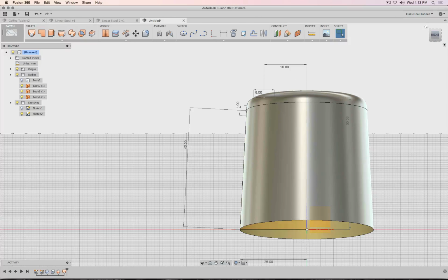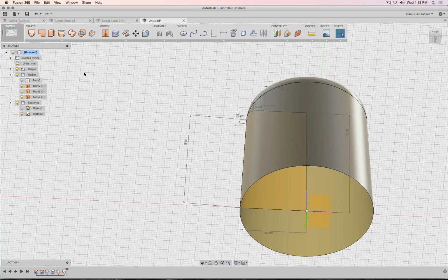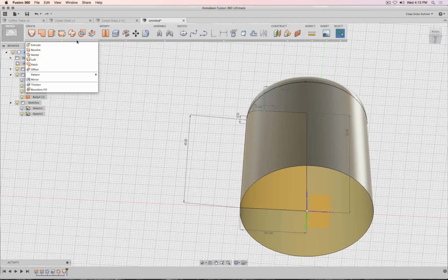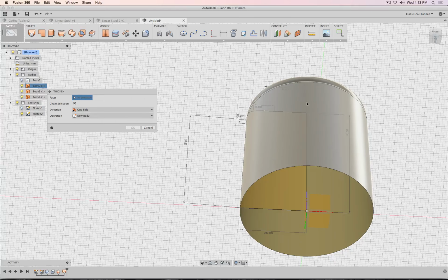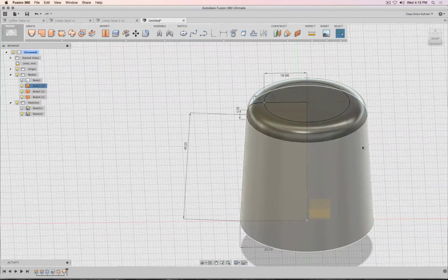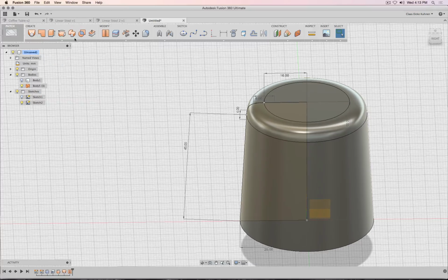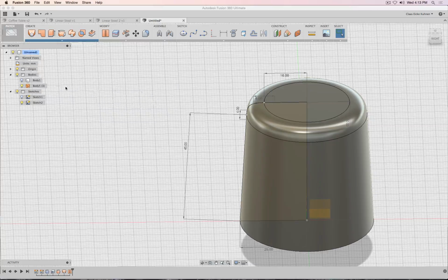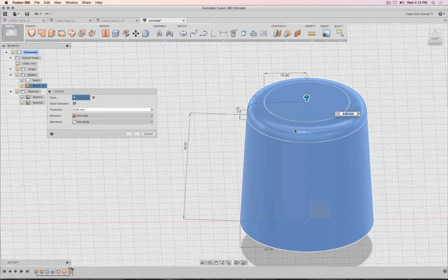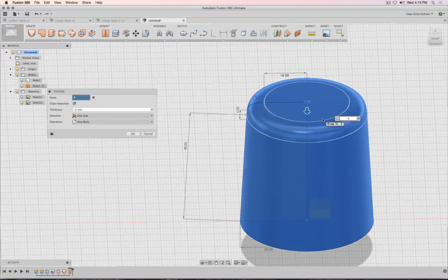There. Now the only problem is I have to create a thickness to it. So thicken this whole part, but it's actually not stitched. So I would have to stitch all those three together. So it's one logical unit. And then I could go to thicken this one to the inside negative. Let's maybe make this one 3.